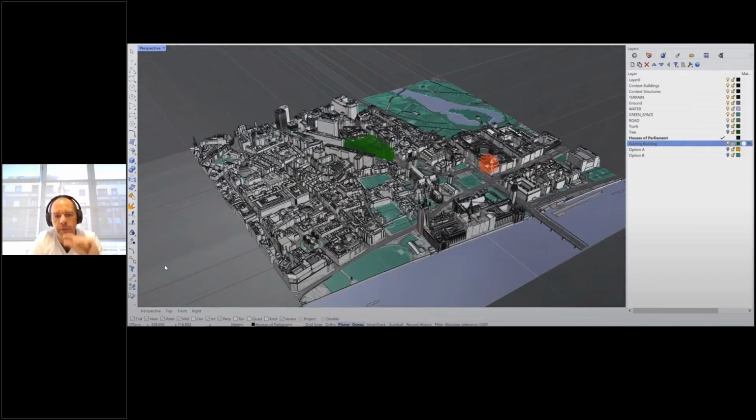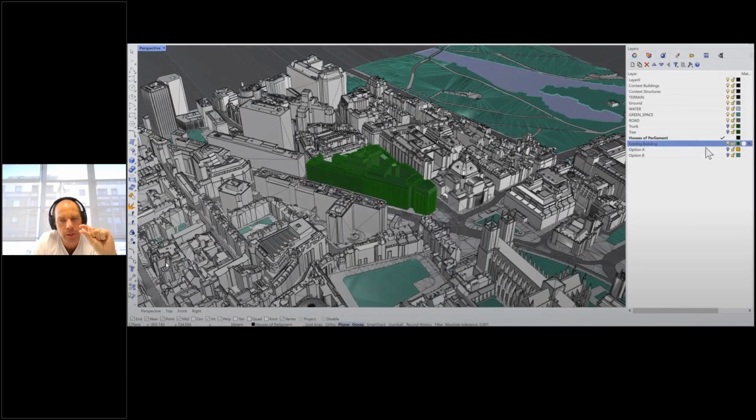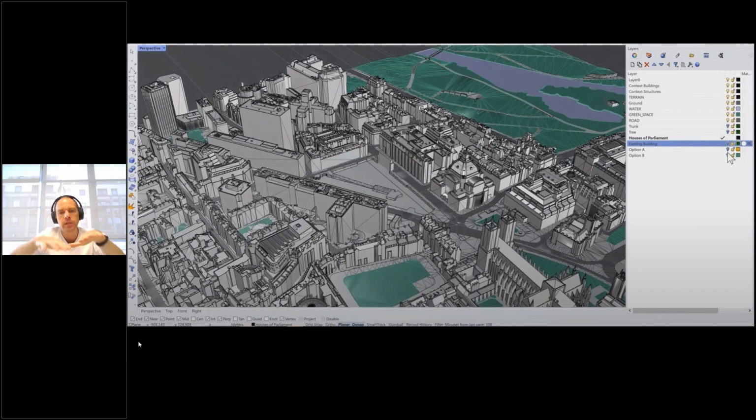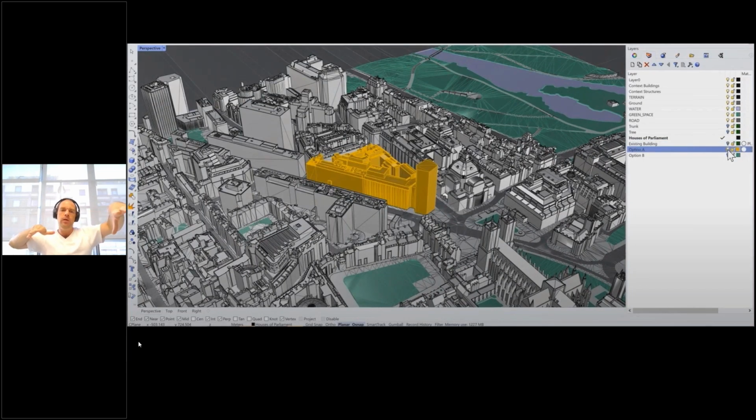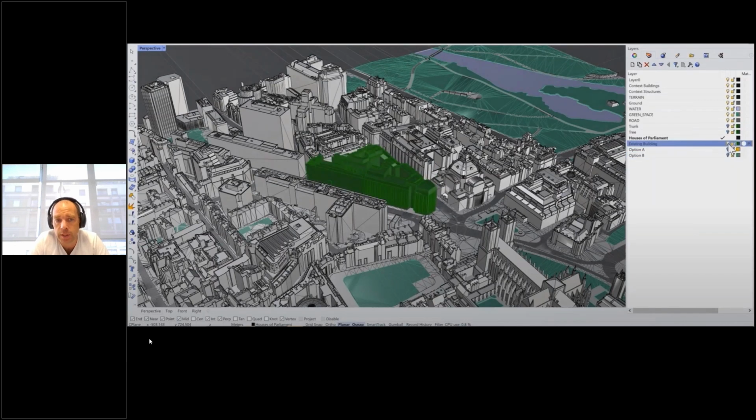Because there's a little elevation change, you do need to extend your ground so that it's larger than your digital wind tunnel. But other than that, and these options, of course, I did not clean anything on this geometry. So that's really the robustness of the LBM solver. You basically save, I don't know, 3-4 days of cleaning up geometry compared to the more traditional solvers.